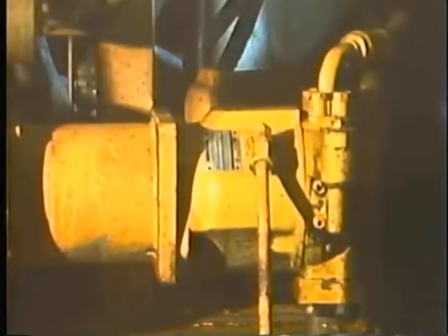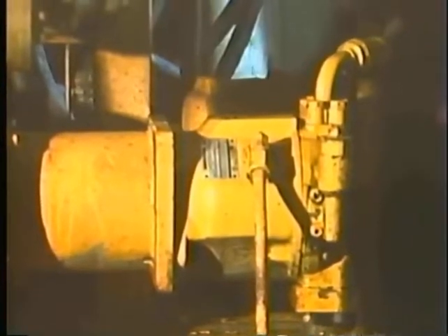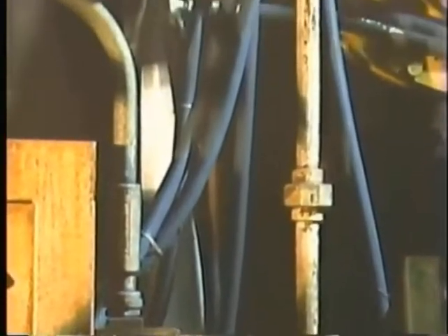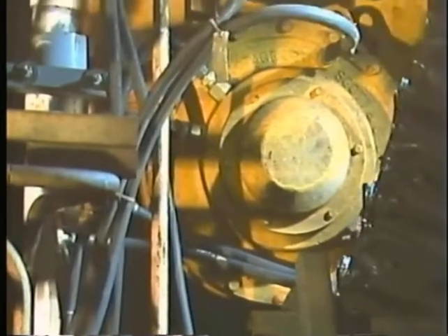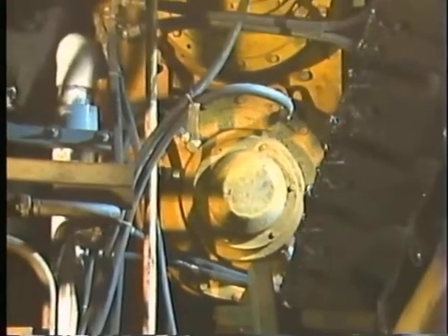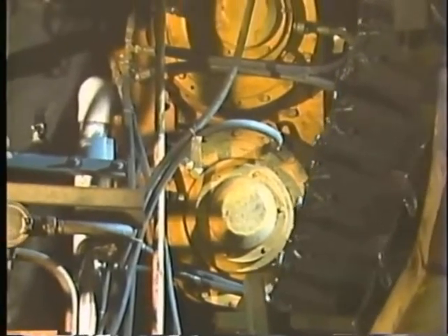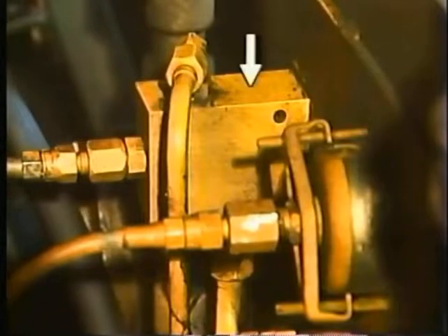As you know, a pump provides the flow of hydraulic fluid at a certain pressure throughout a system. Well, this pressure has to be maintained to help ensure efficient system operation. Excessive pressure in a system could cause flexible hoses or lines to rupture, or seals and other components to be damaged. A pressure control valve, such as this relief valve, is designed to prevent that from happening.